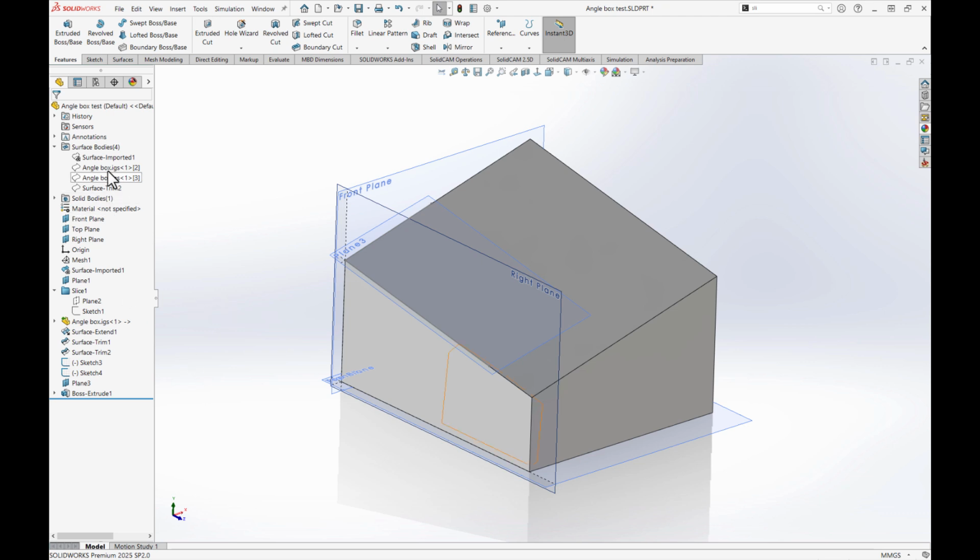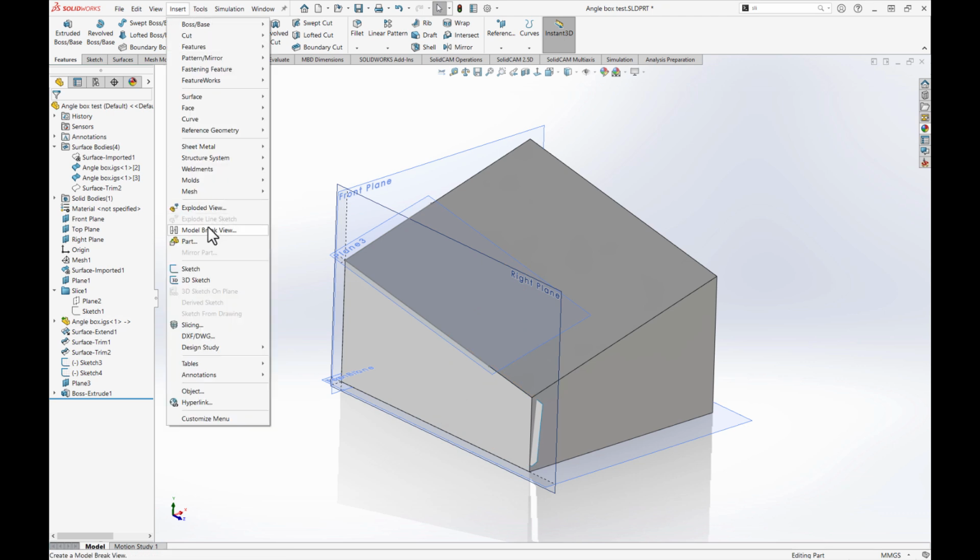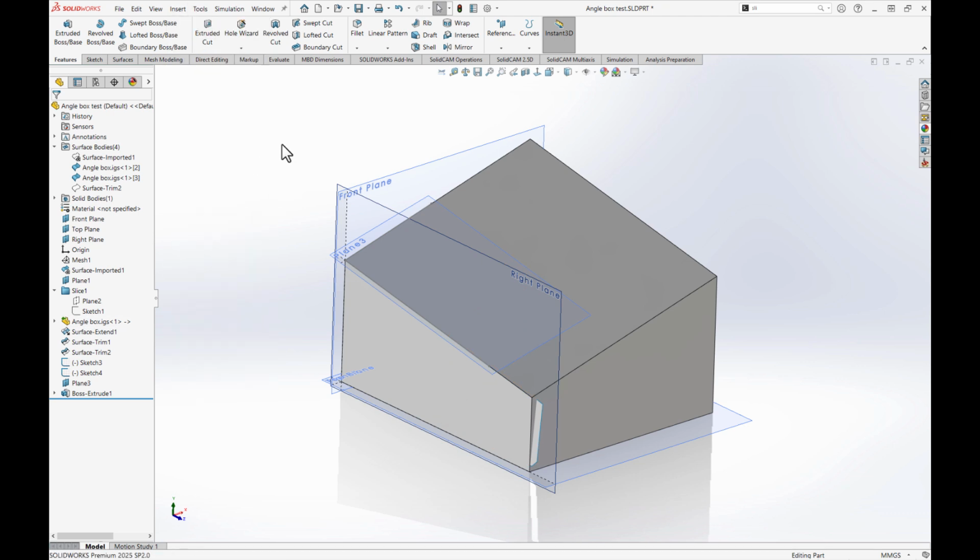So the types that we brought in were all planar surfaces, or in PolyWorks language, planes. But you can bring in cylinders or points or lines out of PolyWorks as well, and they will import just as easily using the insert part method that we just used before. So you can use a combination of the imported IGES features and the imported mesh itself to kind of slowly work your way towards replicating the geometry of that part that you're working on. Okay, that's the end of this tutorial.